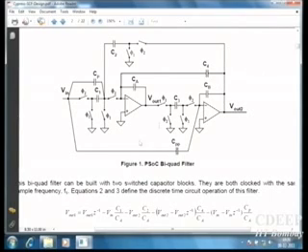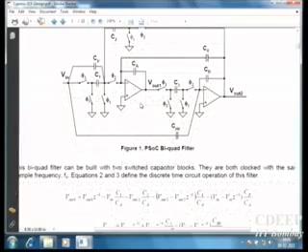In this cascading, now you see the effects. For example, here of course your input has been from some source somewhere, but now for the second stage your input is from the previous stage. So it's very important for this op-amp to have low output impedance. And the current which is required to charge capacitor C3 should be provided by the op-amp.